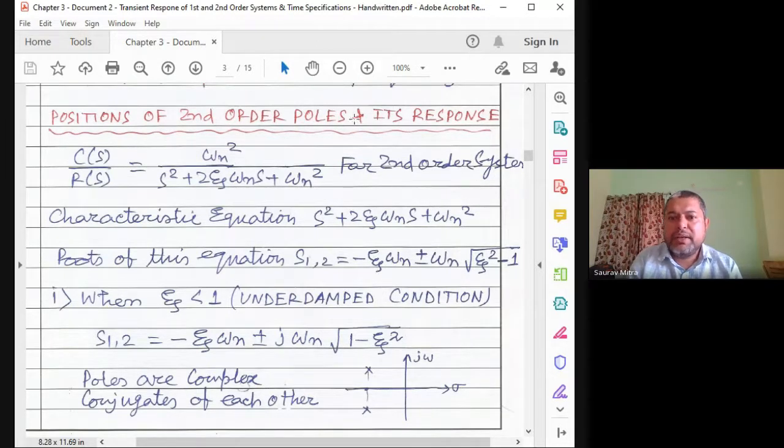So you are doing experiment number 4. If I give you the position of poles, you can tell me what is its time domain step response. Same thing we are going to do here. So this is the second order system response. We know what is omega n. Omega n is 1 by root LC. We know what is zeta, R by 2 root under of C by L.